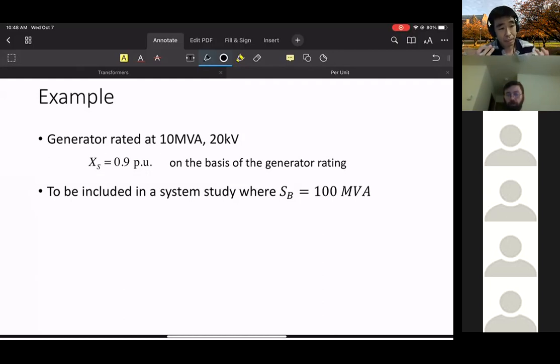Again, remember, this was discussed in the break: for the large system, we normally pick a base unit that's similar to the load we have in the system. So this may be larger than the rated unit for the generator, because we may have more than one generator in the system. Fairly often we'll see this.